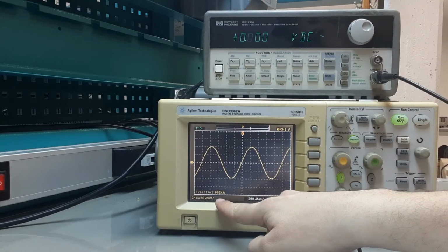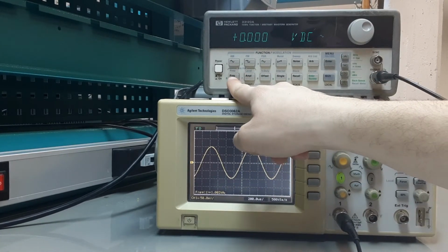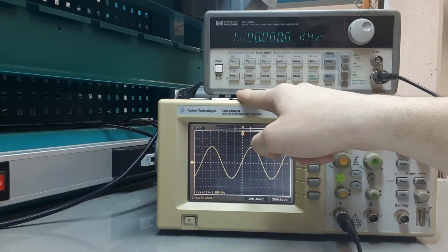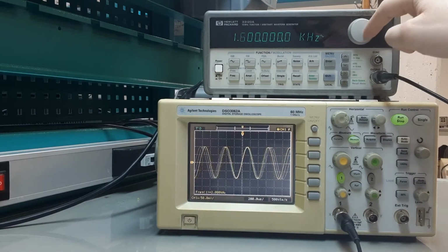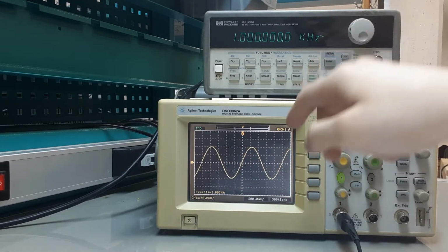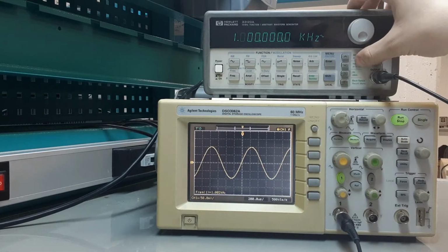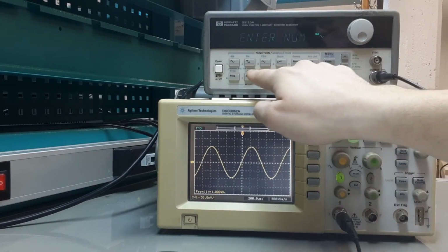As you can see on the oscilloscope, the wave frequency is 1 kHz. To change this, press the frequency button. When you are at frequency settings, you may adjust the frequency by adjusting the knob, or we may directly enter a number, then pressing megahertz, kilohertz, or the hertz button we can set the new frequency value. In this case, we set it to 5 kHz.